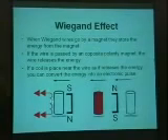And when you wave it next to an oppositely polarized magnet, it dumps its charge, and if you happen to have a convenient little coil nearby, you can actually read that pulse. And that's all that's happening. When you swipe your card through the reader, there's 2 magnets for each row. One charges the wire, the other discharges it next to a little coil.